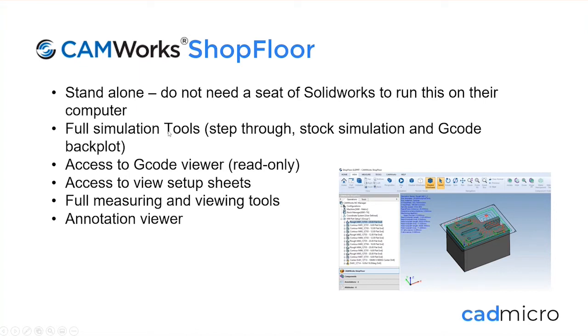It has full simulation tools. So you have the step-through simulation. We have the stock simulation that we have in CAMWorks. And we also have the G-code backplot from the NC editor. So full simulation tools, access to the G-code viewer. So again, this is the NC editor that we can open the G-code up and take a look at the actual code.